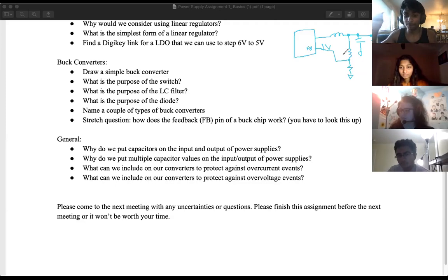It's taking in the output voltage and saying, how close is this to 1 volt on this resistor divider? If it's greater than 1 volt, it's going to back off on the duty cycle. If it's less than 1 volt, it's going to put some gas on it and increase the duty cycle. Gotcha. So it's our job to set those resistor values based on the actual output voltage that we want. Precisely. The data sheet usually does the math for you there.